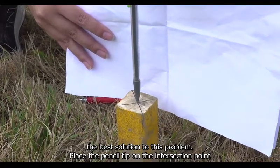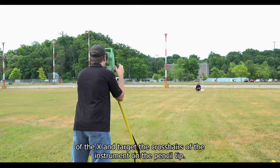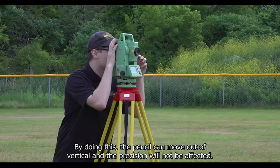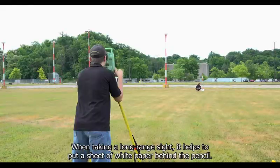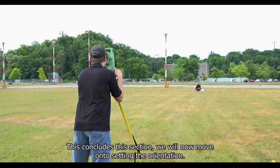Place the pencil tip on the intersection point of the X and target the crosshairs of the instrument on the pencil tip. By doing this, the pencil can move out of vertical and the precision will not be affected. When taking a long-range sight, it often helps to put a sheet of white paper behind the pencil. This gives a better visual contrast and makes it easier to precisely target the point.